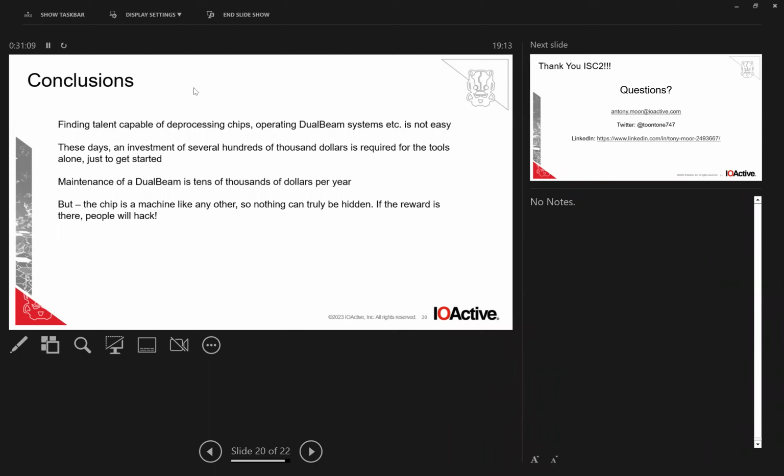Yeah, I would agree. The bulk of pirates will just send samples to China and they'll get the images sent back. They do it very efficiently. They have a lot of people. I mean, for IOActive, we're doing things much smarter, trying to automate things so we can do this very cleverly. You take one chip, you remove one layer of circuitry so that hopefully 100% is visible. Then you image it once, you take off another layer and you image as you go down.